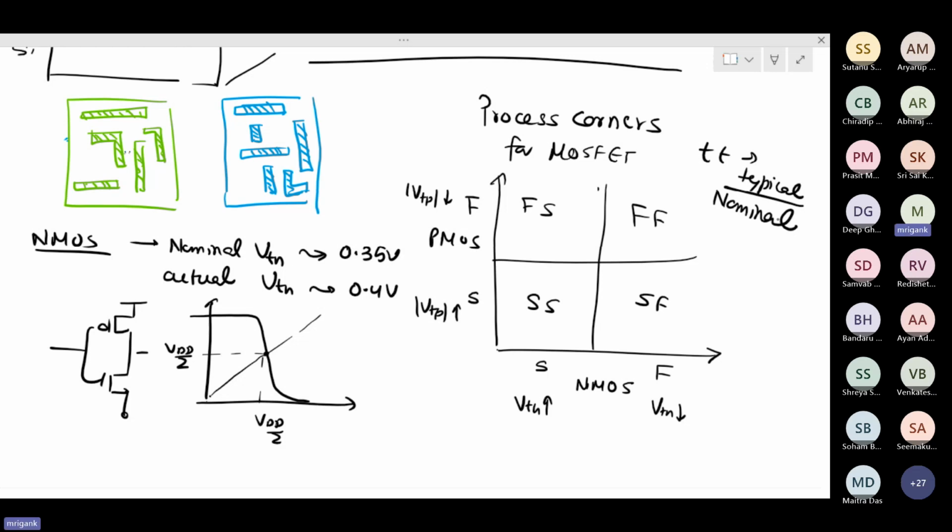In this LTspice, you may not get that kind of model. Right now in this model, you don't have this corner setup. But if you want to emulate, you can always emulate. Just like, if you want to lower the threshold voltage VT in that model, you can go and edit the VT value or the doping value. In the 45 nanometer model which you sent, it is there in the text file: slow, fast, and typical. Okay, that is there. Then it is good. So in that case, you can do it directly. Otherwise, in the older models, you can directly modify the VT value.